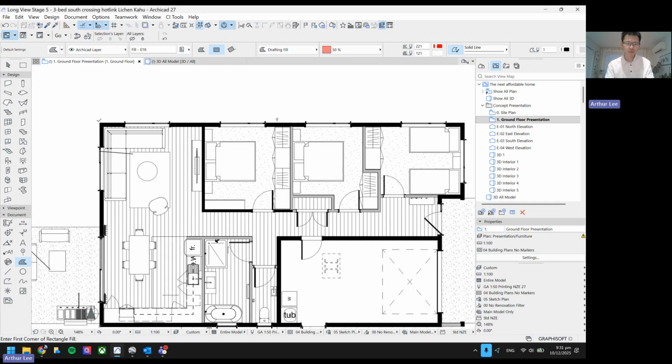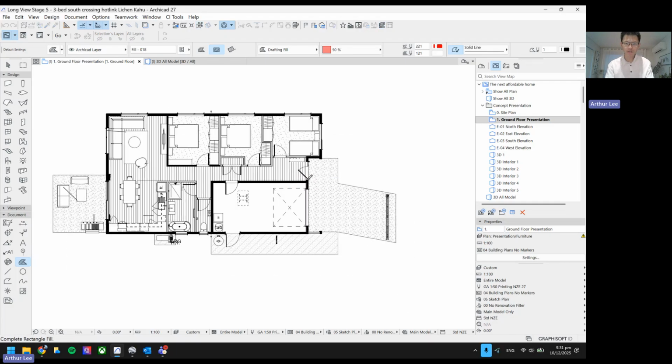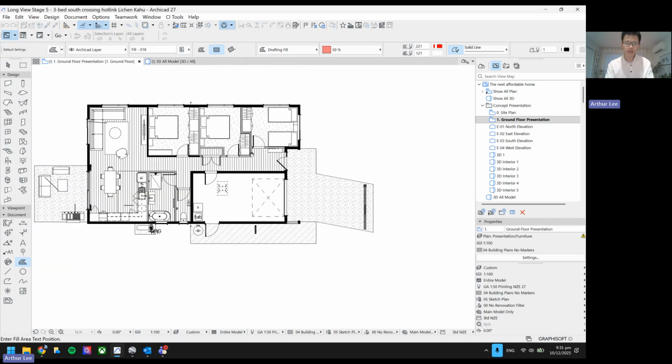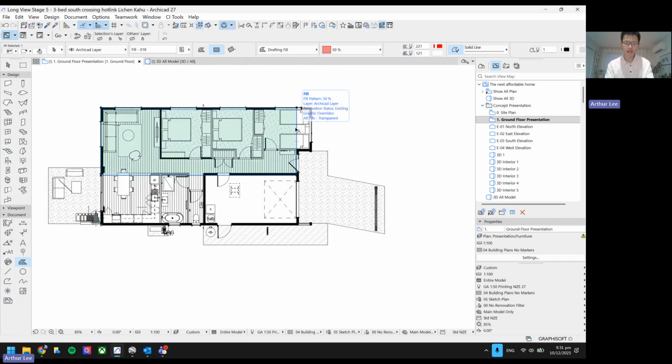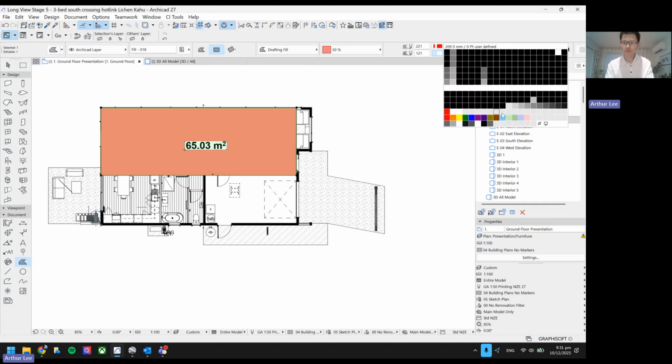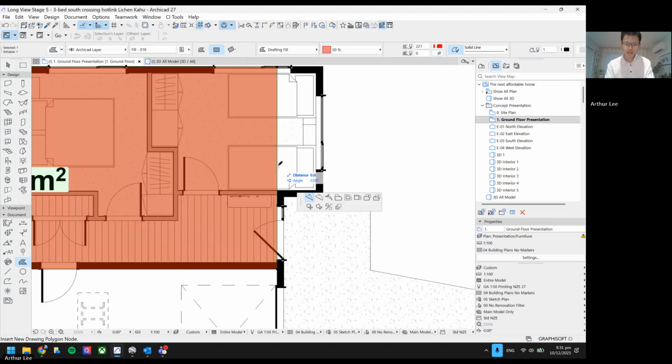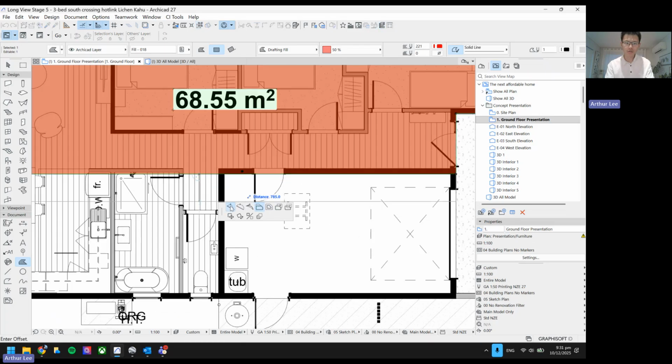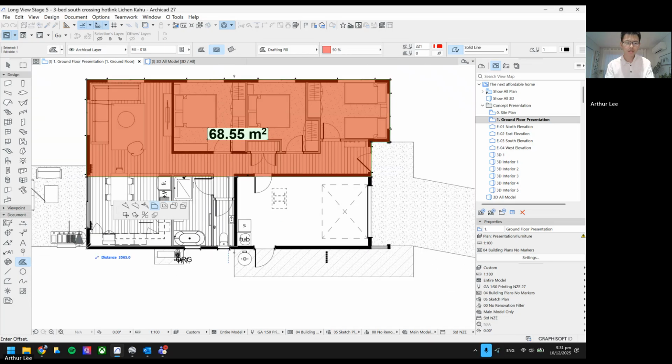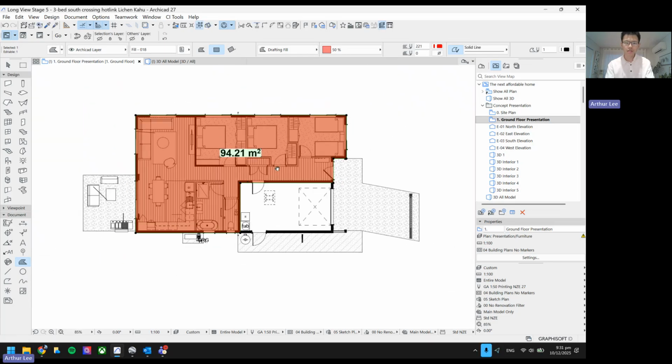With the BIM model, I can easily measure the floor area. In this case, I need to highlight the floor area is and should be the area of the thermal envelope, not the total building footprint. So in this particular case, I do need to exclude the garage. Now this is the gross floor area, and what we need is the conditioned floor area.